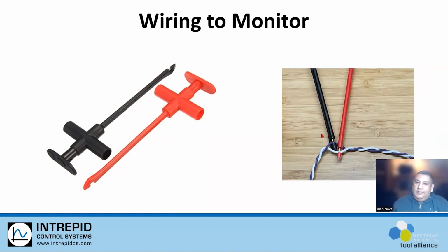Now, this is a little bit destructive, so I'm always going to recommend that you use a breakout box or a breakout harness in order to avoid doing this. That way, the harness is the one that you're really interacting with your connectors. I don't have a really good example to show you of a breakout harness or a breakout box. Everything that I found online has copyrights, and I don't have one where I can show you this. So in this case, this is what I had to show you.